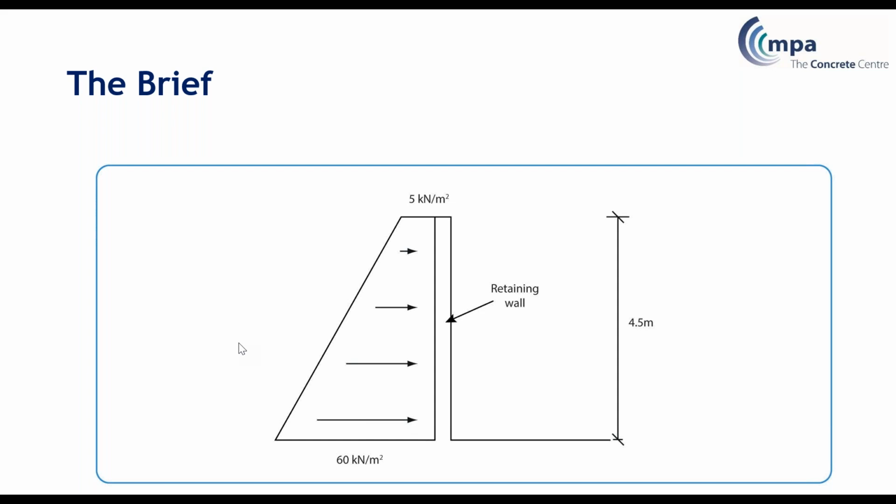So this will form the biggest proportion of horizontal load on the building, and you need to take account of it. Work out what you're going to do with it, where the load is going to go. So it's worth putting in where you're going to take that load to, how you're going to resist that load, as well as obviously there's vertical loads that you will need to work out how to resist. One of the things you could do is to show by little diagrams where you're taking the load. You don't have to, but it's just one of the things you could do.